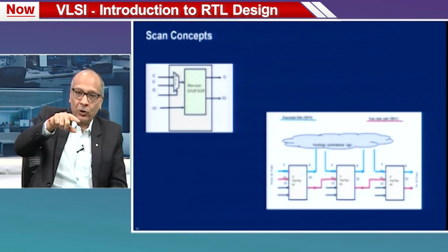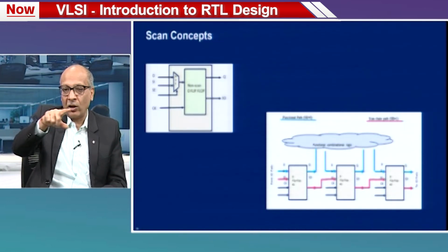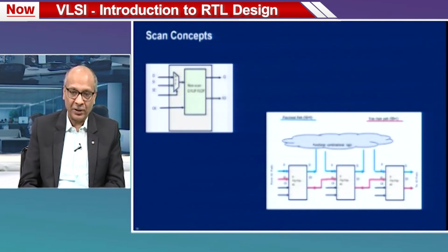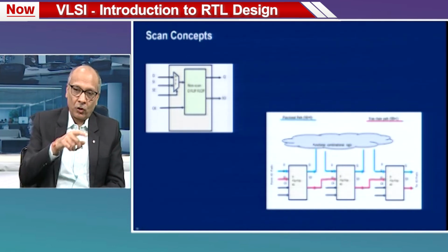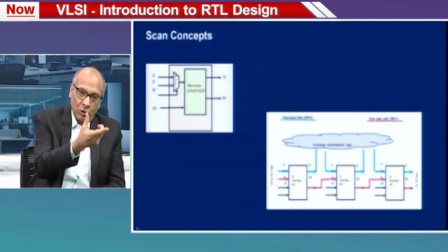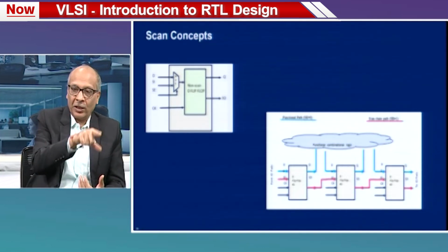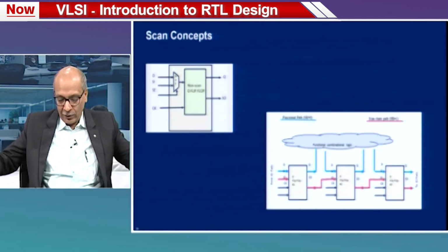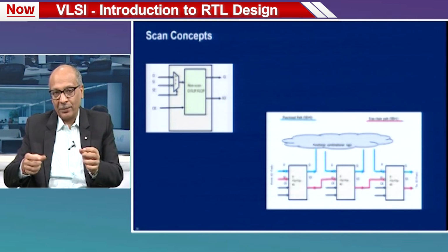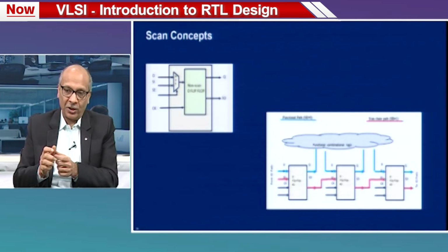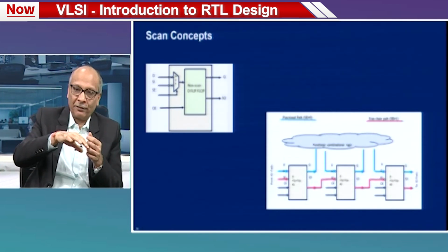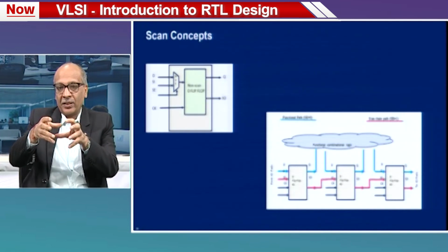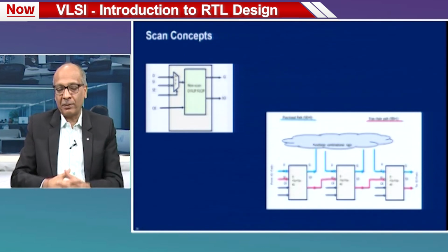The patterns that are used to send this are called test patterns, and that technique is called automatic test pattern generation, ATPG. Okay. So, there will be tools which will generate the automatic test patterns, which is what you will give to the tester equipment. These are very costly machines. So, you have gotten this fabrication done, so many devices are coming and you want to test everything very quickly on very costly machines. So, your vectors should be such that they are efficient and can test things very quickly. That is why you add this extra scan based mux and establish scan paths.